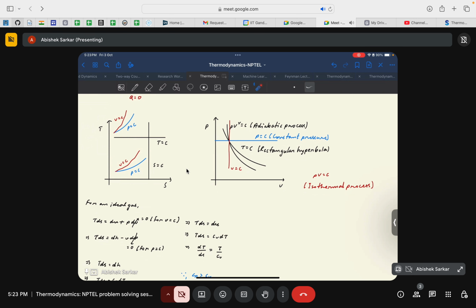that especially when we discuss the Otto cycle and diesel cycles, there are processes which are specifically mentioned to be a constant pressure process and a constant volume process, especially in the diesel cycle. In that case, the slopes of those processes in the PV and the TS plots, sorry, in the TS plot, specifically also matter. We need to show them clearly. For example, if you do a PV plot and draw the constant pressure and the constant volume processes, sorry, in the TS plots, you need to be consistent in the slopes of those processes.